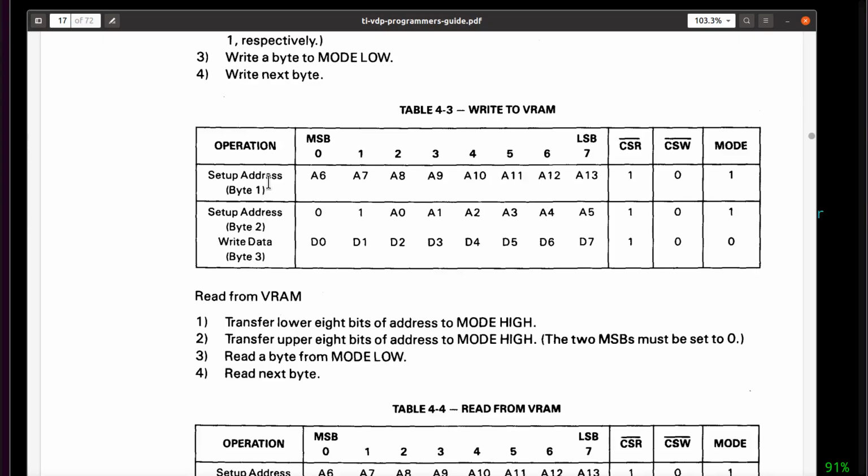The idea that I want a 1 byte, then another byte, we have to keep track of that in our code. And we have a 1-bit value that says I'm in a state waiting for the least significant byte, or I'm in a state waiting for the most significant byte. You're always going to be waiting for one of those 2 values when there's a mode 1 write access going on to the VDP. The same is true for the configuration registers. That has the same problem. What if you write an in that case, it's a data byte.